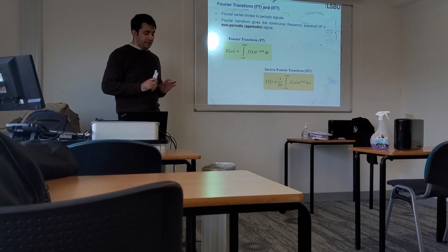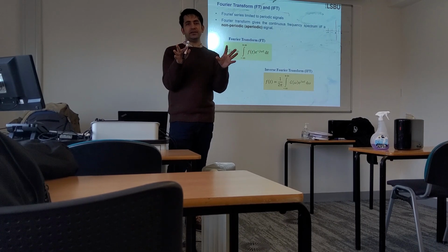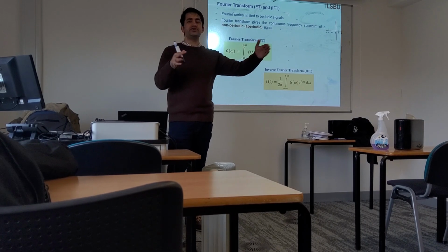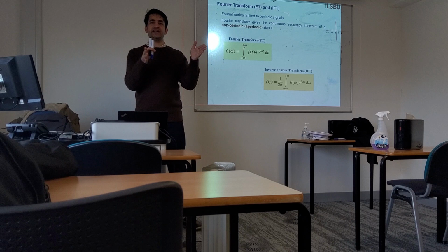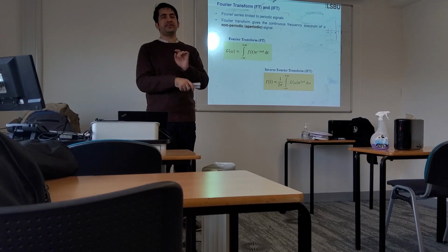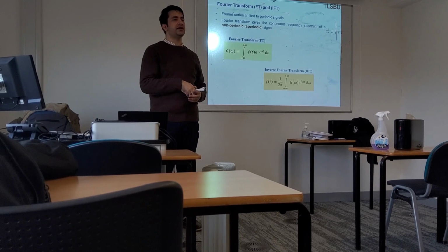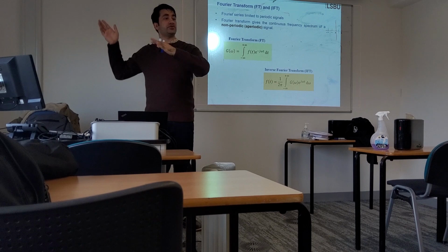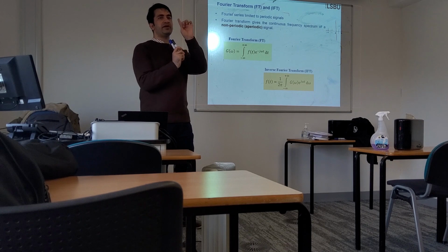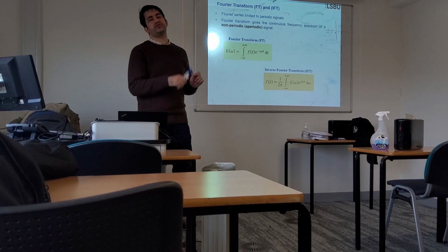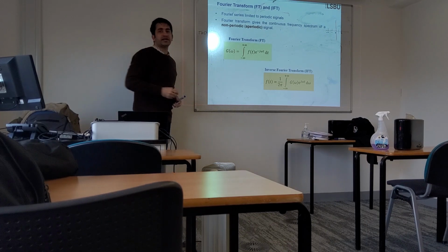So now again, if someone gives you two AC supplies, and wants to ask you which one is better, looking at them, we cannot judge it. But once we do the Fourier analysis of its output, we will see, okay, this supply is giving me 50 Hertz, but also giving me, let's say, 100 Hertz and 150. So there are many other frequencies. So I will clearly say, okay, no, this is not good because it is not giving me a fixed frequency. How am I going to know that? Using Fourier transform.